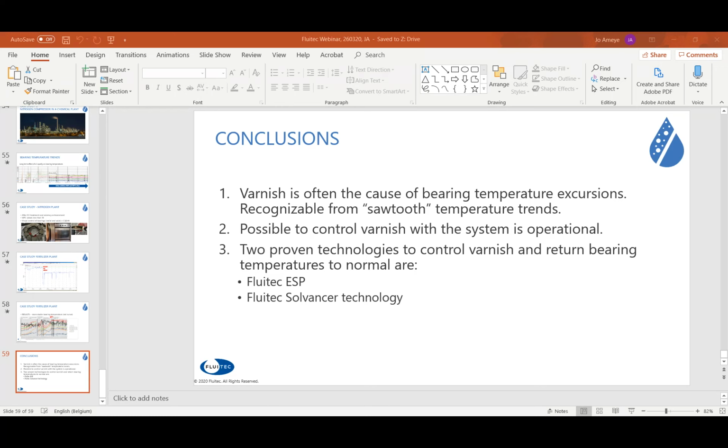What we have seen is that the residence time of the oil in these seals is longer. If you have oils with a little too high amount of oxidation products, deposits, MPC if you want, due to the longer residence time you have a risk of them staying longer in those seals and creating deposits. We have seen this also on hydrogen seals, with more deposits because these contaminants stay too long at too high a temperature. They will agglomerate and form these typically brown, black deposits on seals. Absolutely, so watch them and keep your oil clean.